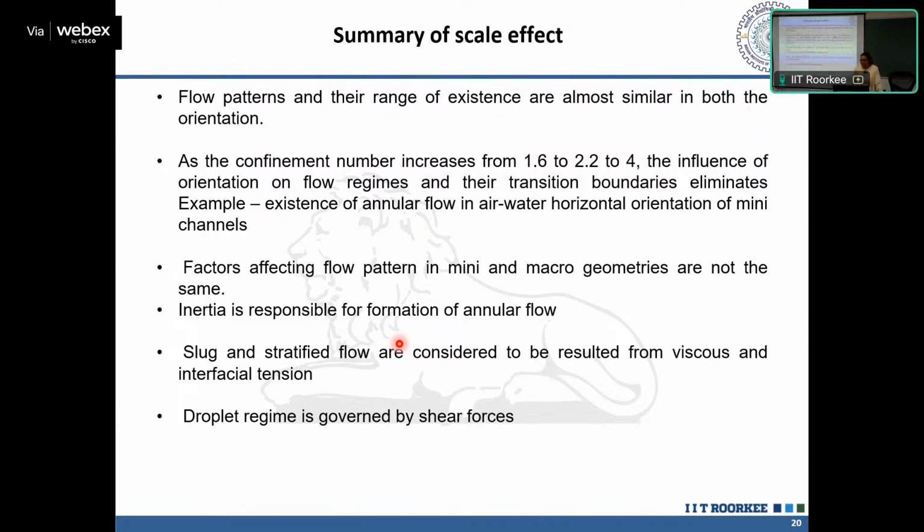So, in summary, the factors affecting mini and micro channels are not the same. What we observed is that inertia is responsible for the formation of annular flow. Slug flow results from viscous and interfacial tension forces, and the droplet regime is governed mostly by shear forces.